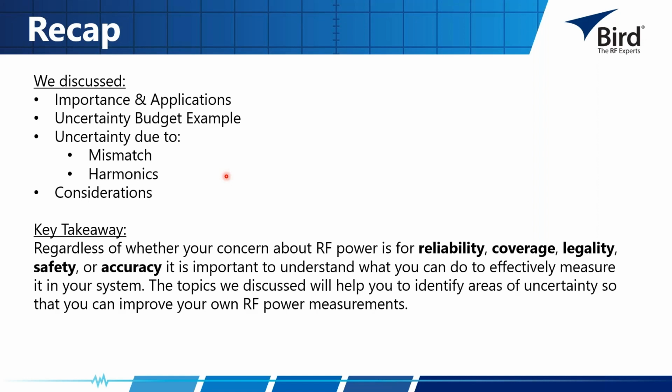Okay, let's see. We have a little more time. It says, what is the difference between error and uncertainty? Error is, you could think of it as, you take a measurement and it is incorrect by some amount relative to a true value. Even though it might be hard to measure it perfectly, there is a true value that a source is actually putting out, and whatever our measurement device is displaying, there's going to be some offset, and that can be accounted for.